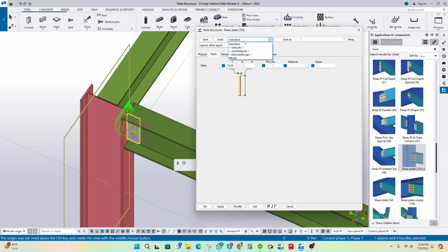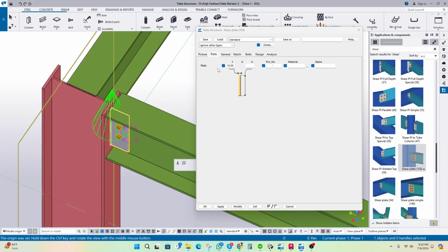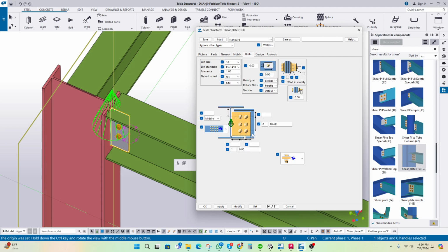And for the plate, what kind of plate I need, the thickness of the plate, I will provide. No need to provide the HSS height or something. If you want to provide it, it's okay. If you don't provide it here, then you can control it from the bolts from here to here, because there are already standards. Usually I never provide this one, because if I provide it, it makes the drawing difficult.